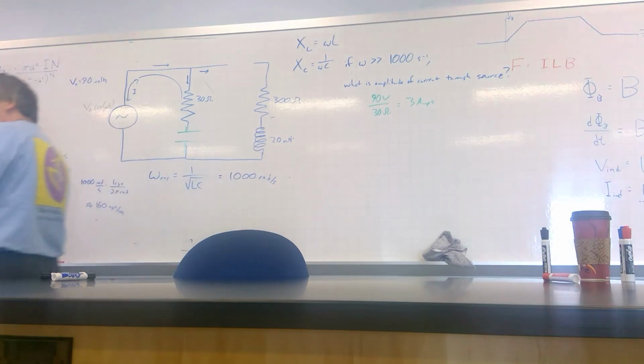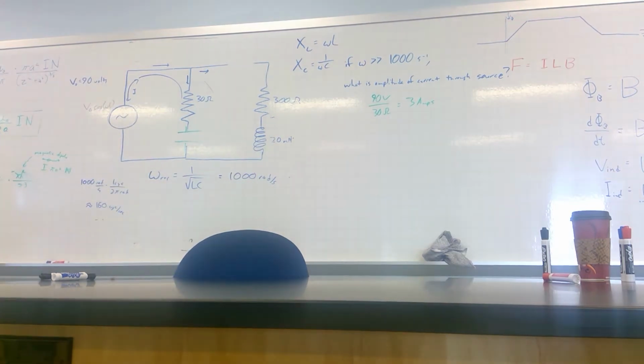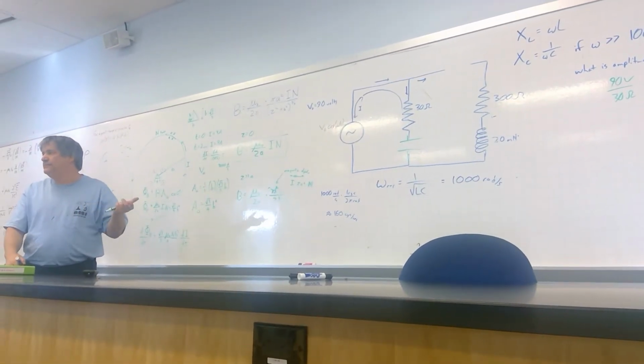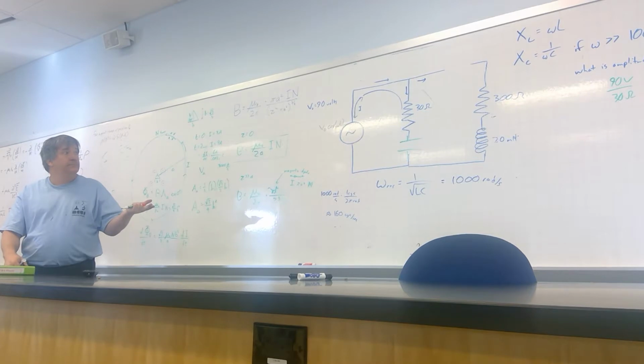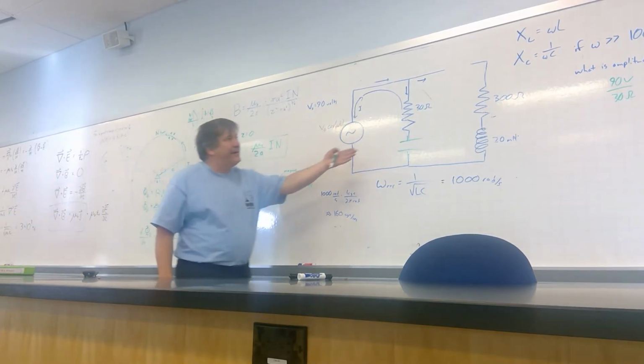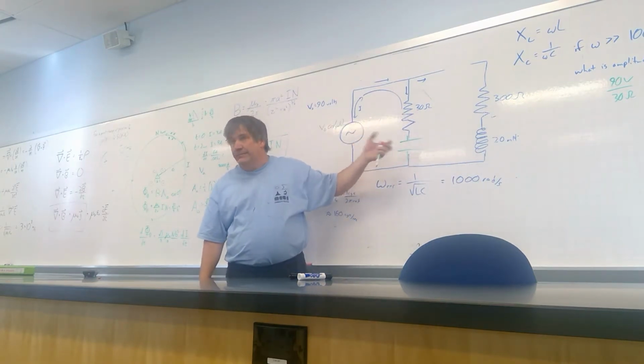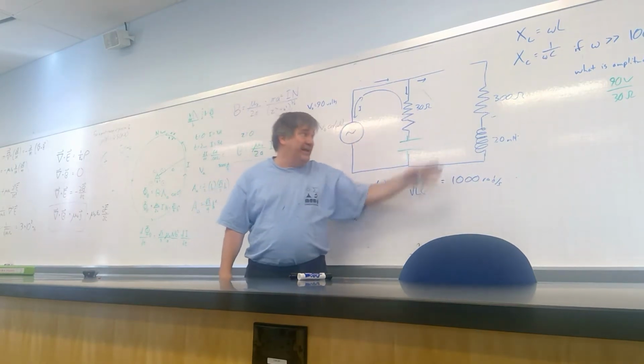So just to clarify, when the high frequency causes the inductor to be short or breaking the circuit, then the only impedance would be just that one resistor, not the other resistor. Right. This resistor no longer matters because it's in series with a break. This resistor does matter. And again, it's not truly a break.